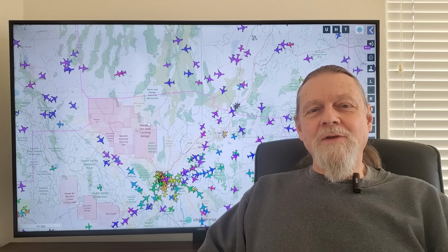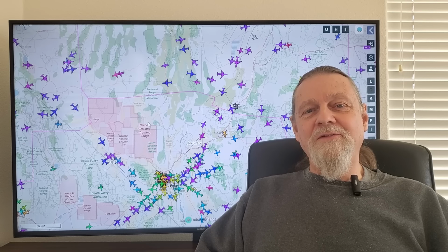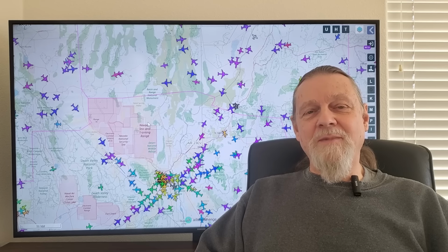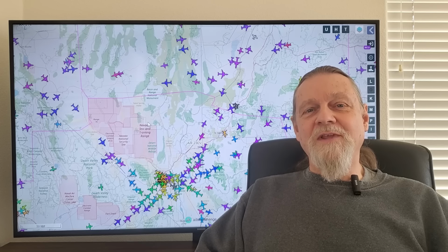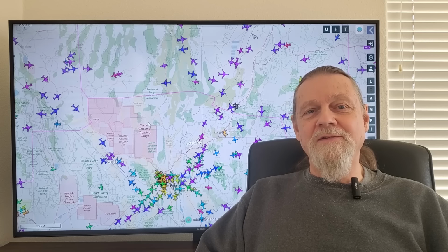Well, howdy folks. Most of you have probably seen or maybe even used websites like ADSB Exchange, where you can track aircraft in real time. That is made possible by a system called ADSB, or Automatic Dependent Surveillance Broadcast. Basically, it's a system where every aircraft in civilian airspace transmits its position and some other data on a certain frequency to enable air traffic controllers to track it and, of course, to avoid collisions.